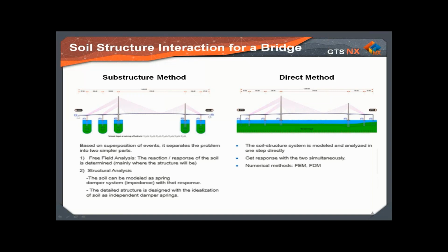The soil dynamic stiffness coefficient can be physically interpreted as a spring damping system. This stage corresponds to the evaluation of the kinematic effect, so the structure and foundation lack mass but have rigidity.